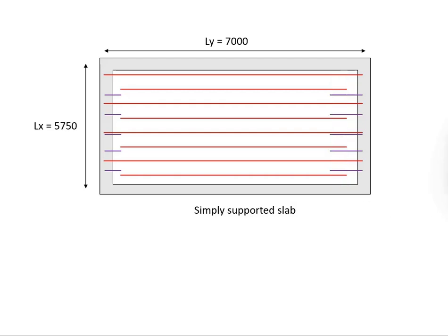This lapping length will lead to a waste of material. This is the second issue. The first issue is the random arrangement of the reinforcement bar here, which doesn't seem consistent with the initial spacing. Second issue, you need the lapping length.